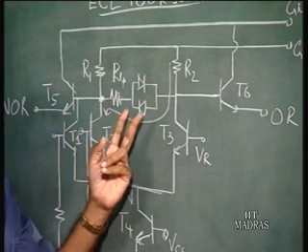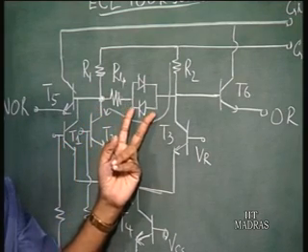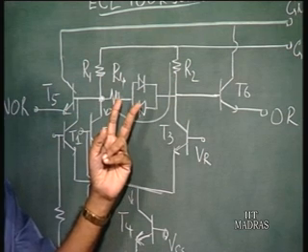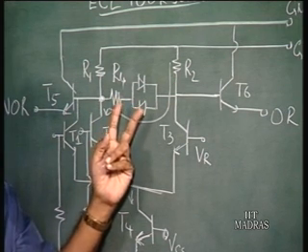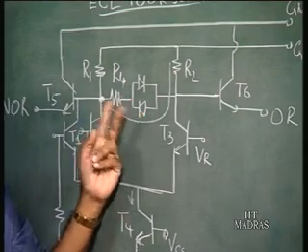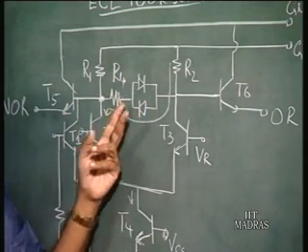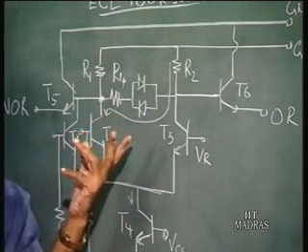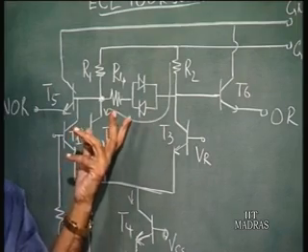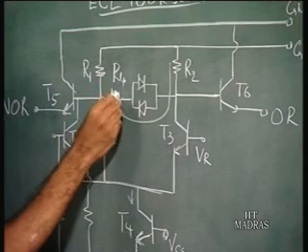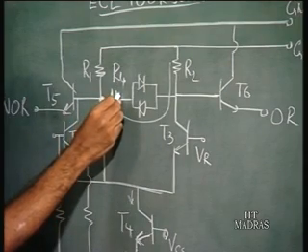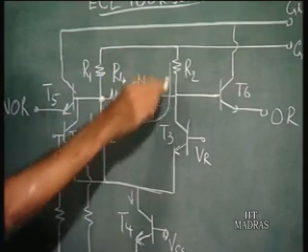In fact, this diode in this path also has the same temperature dependence of VBE, of the drop across the diode. So, basically there is going to be a drop corresponding to, say, 3 millivolts per degree centigrade. And if you assume R2 is equal to R4, because of this increased current flow,